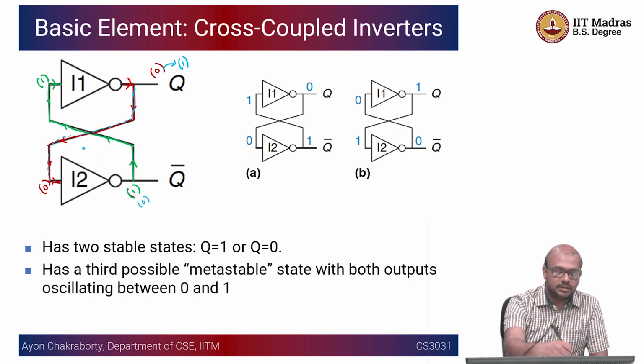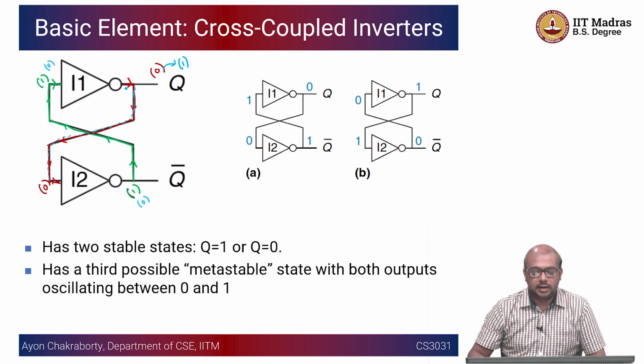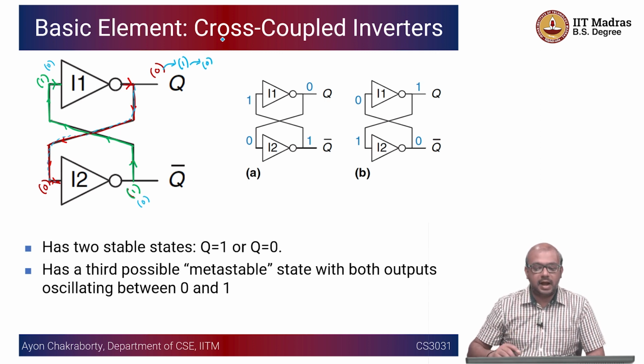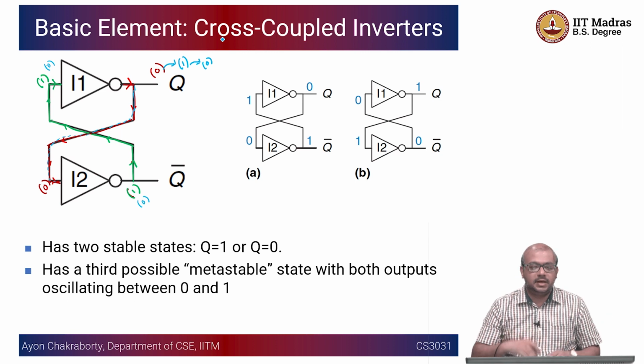Because now if this is written as 0, this will again become 1, but originally it was being shifted from 0 to 1, right? So there is some amount of oscillation that might actually be present, and at the same time you might have oscillations in the data itself, right? Again, 1 can become 0, 0 can become 1. So in that kind of a case, because of the way the signal propagates, there could be an oscillating stage. It is not stable. Okay, so 0 becomes 1 and again 1 becomes 0, but in the meantime things will change and kind of conflict with each other.